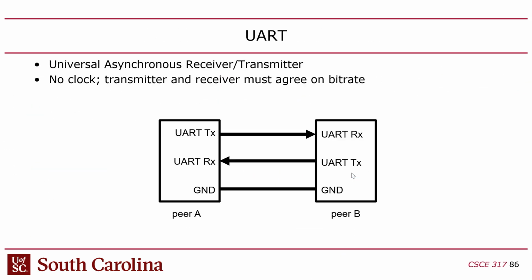But before we get to that, I want to talk about UART. This is another protocol, and this one is notable for being an asynchronous protocol, which means that there is no clock signal embedded in the channel by which the chips synchronize.